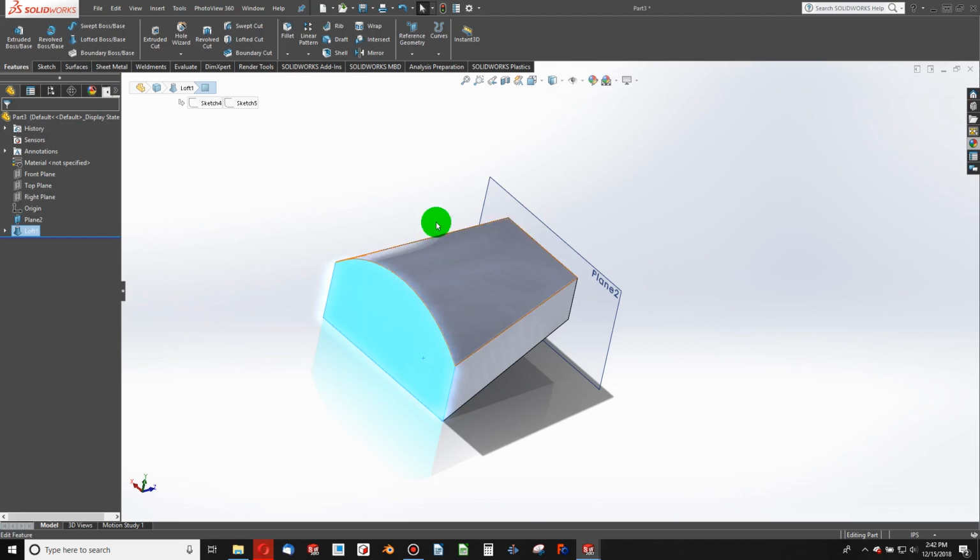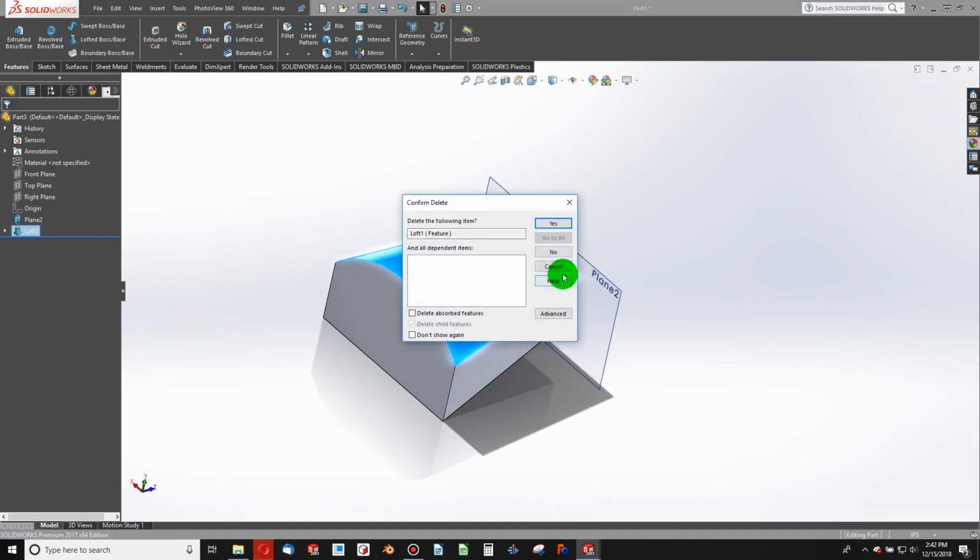The other thing about lofting is sometimes profiles can be too complex to loft, right? A solid loft just can't keep up with the complexity. However, doing the exact same loft as a surface and then making it thick later will work. So surfacing allows us to run the same loft function on a more complex profile and be able to do it, whereas a solid wouldn't be able to keep up. So let's run through an example.